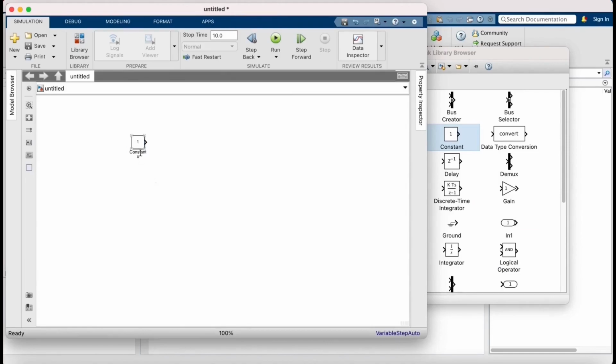These names at the bottom of these blocks, while they need to be unique, they do not have significance in Simulink. Because in Matlab, for example, if you have the variable x, that's the name of the variable. Out here, it does not actually work like that. This is really just more for us to be able to see it. Okay, and then you can go grab another one, or else you can Control C, Control V, so copy and paste just as you would in any other program. Click, and then I'm just going to call this y.